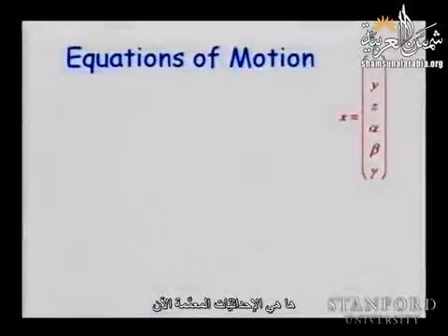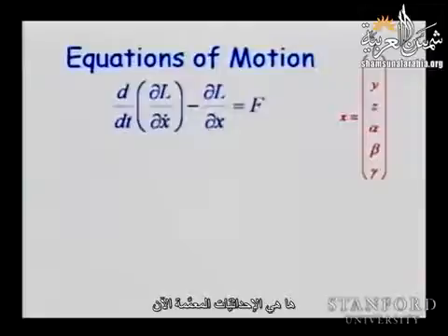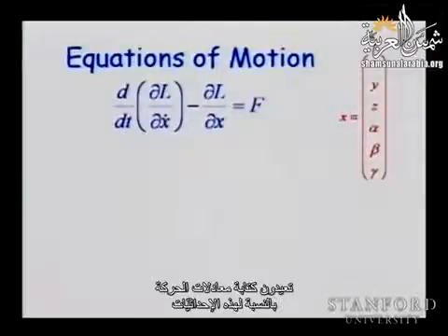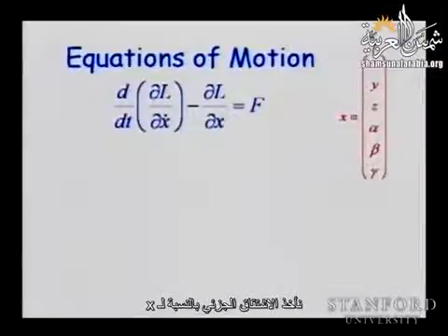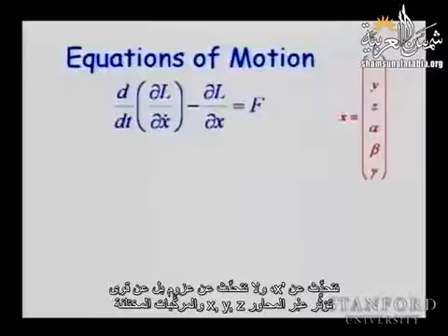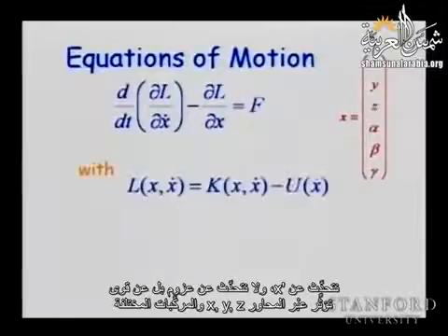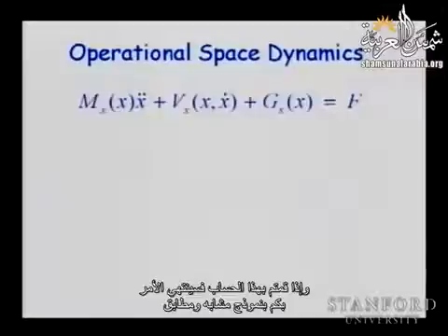Here are your generalized coordinates now. You write your equations of motion with respect to those coordinates. We're taking the partial derivative with respect to x. We're talking about x dot. We're talking about not torques, but forces acting along x, y, z, and the different components. And if you do this computation, you end up with a similar, identical model.